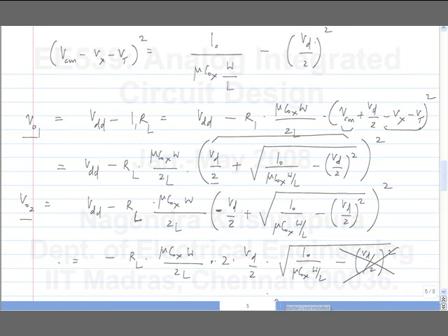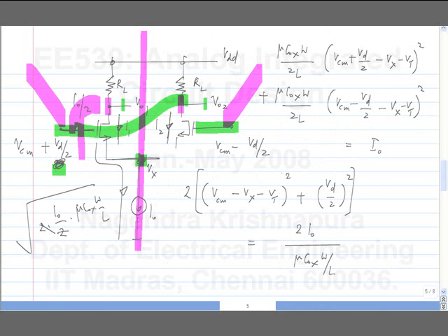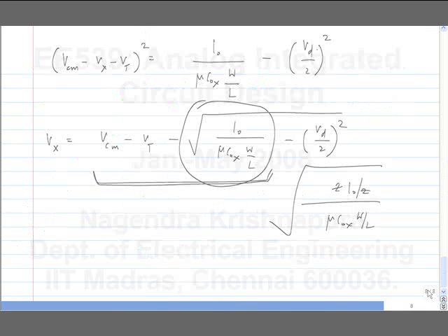So we have Vcm here in the quiescent condition and Vcm minus Vgs is the tail node. By the way, this node is known as the source coupled node or the tail node of the differential pair. So that is nothing but Vcm minus Vgs, which is Vcm minus Vt minus the overdrive. But in presence of Vd, we will have an additional term, minus Vd square by 2.